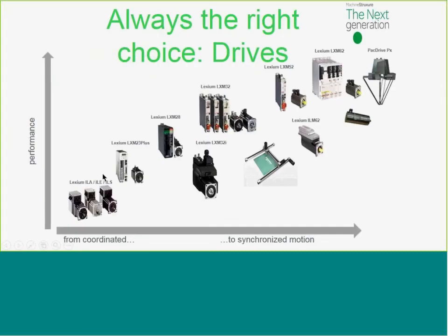This sort of goes into our servo drive and stepper products. We have some integrated, low-cost, standalone products with the drive, communication, and motor system. These integrate to Schneider control systems and a variety of other control systems for set-up axes, typically. And we have some standalone servo drives, the 23, 28, and the 32. They have a BCD-coded input or a fieldbus connectivity to give them positional information. These are typically used in sequential type move applications.